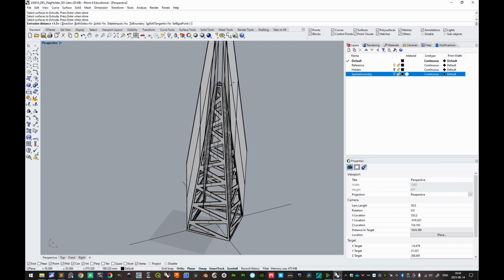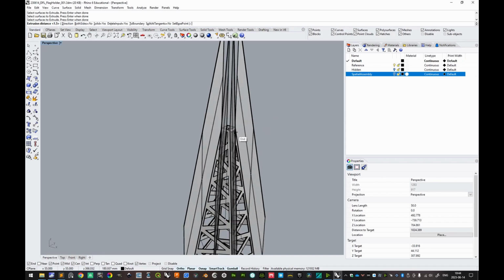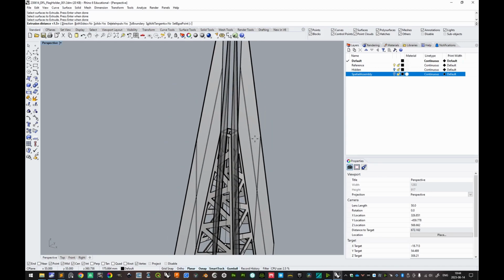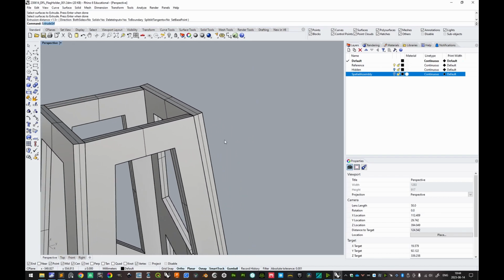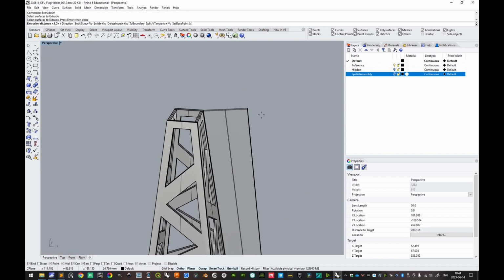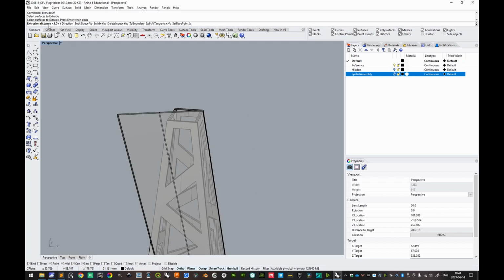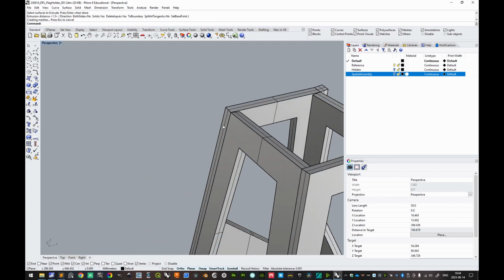If you do it with a multiple selection, then there is not a default normal direction. So we want to just hit escape on the keyboard, and then do it again. It doesn't take that much time. Take first that one, only that one, and then it's going to be the normal direction. And then since we already have the 1.5 millimeters extrusion distance, we can simply press space on the keyboard. Very good, and we'll do the same here.